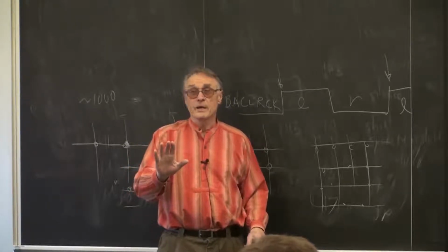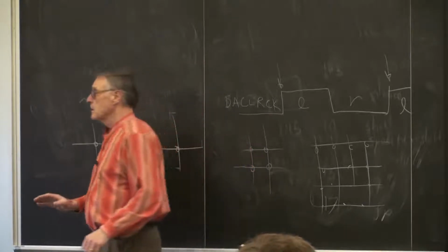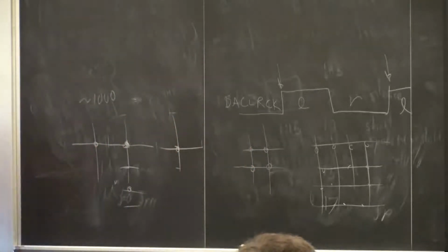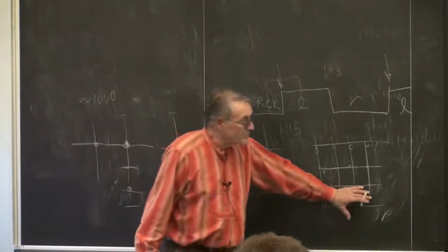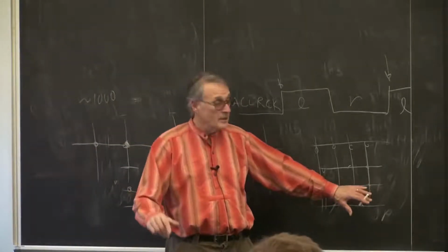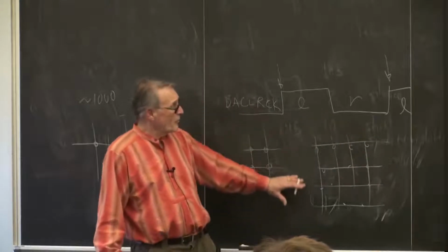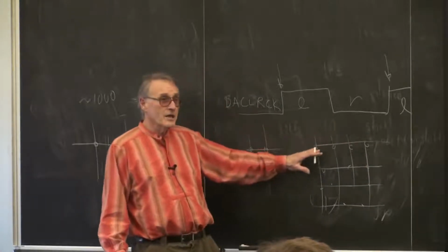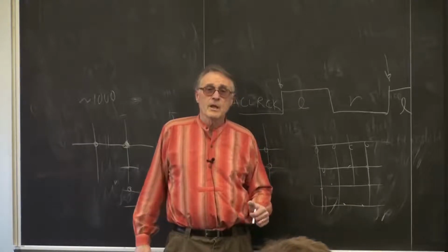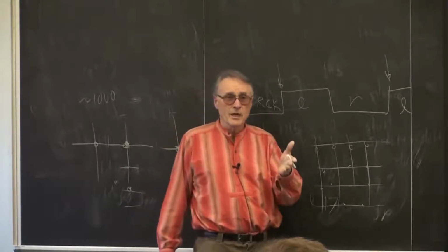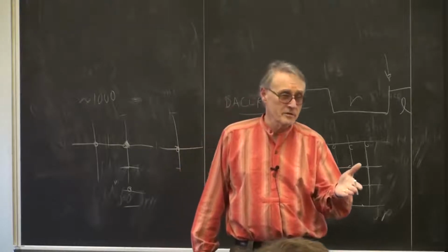The memory block, it turns out, is, well, that's what we need to talk about, because the size of the memory block might determine how big a block of nodes you want to update with one state machine. And since you're using M10K blocks, you're not using up logic elements for storage.